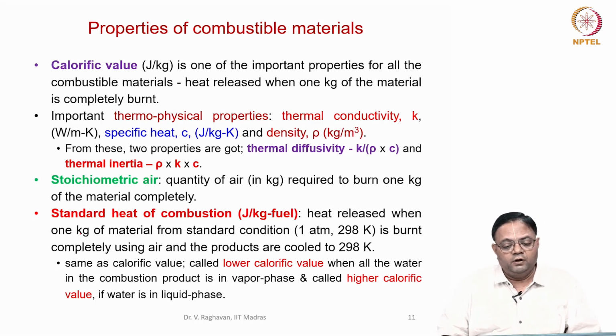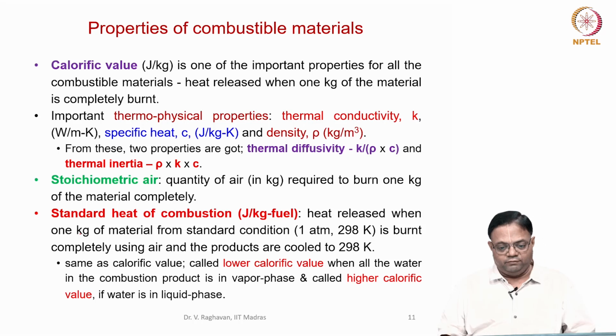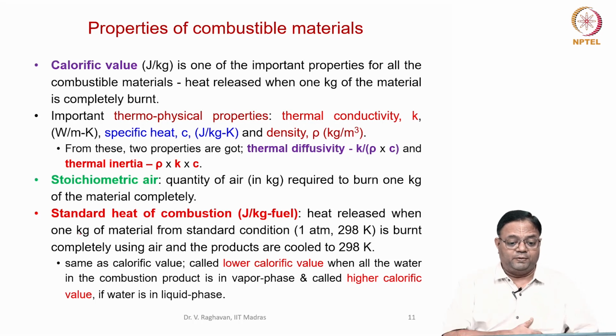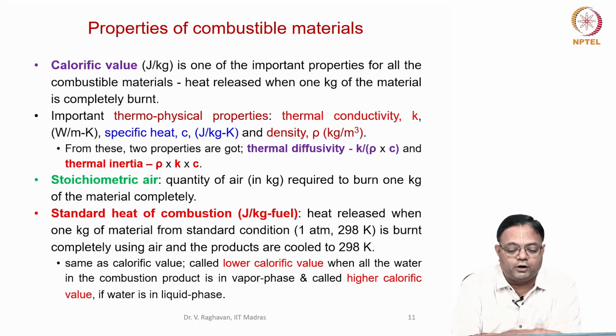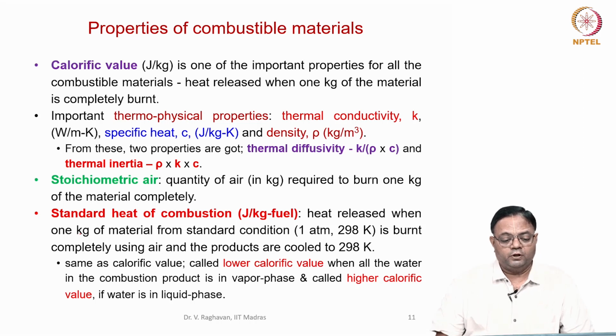Then you have other important properties, which as a group are called thermophysical properties. They are thermal conductivity K in watts per meter Kelvin, specific heat C in joule per kilogram Kelvin, and density rho in kilogram per meter cube. Okay. So, now these are all very important thermophysical properties of the fuel.